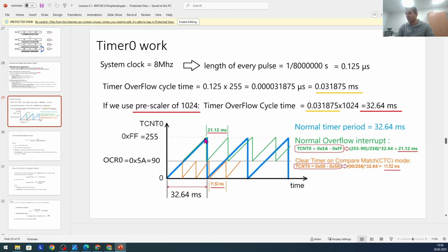So with the overflow interrupt, we limited the timer to move over the green wave, for example. And with OCR0, we decide when to turn off the output. We set the output in the overflow interrupt. Then we have to turn it off somewhere also. So we can put the OCR value here, depending on the push buttons when we increase or decrease the OCR0 value. This is the compare value.